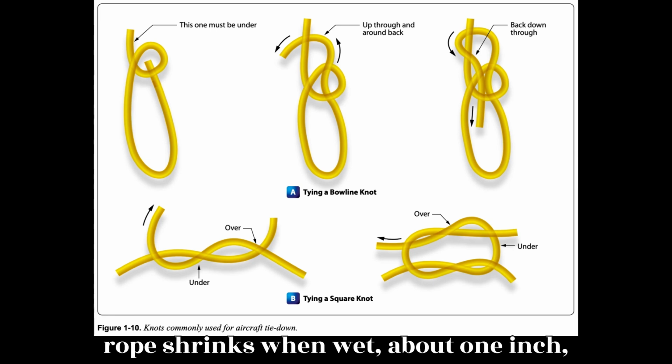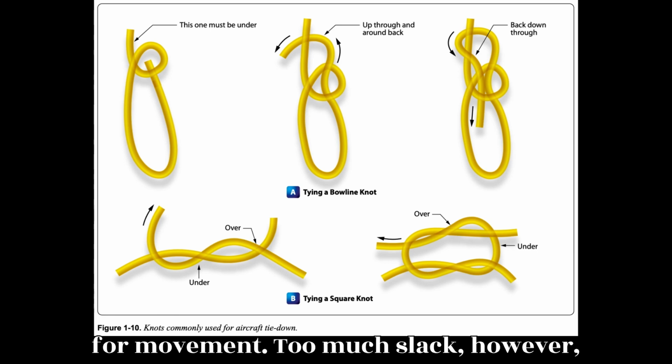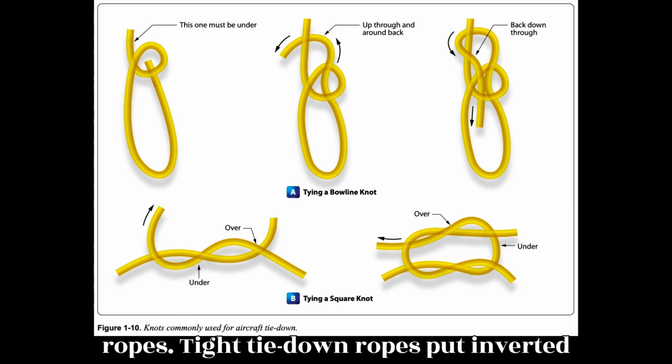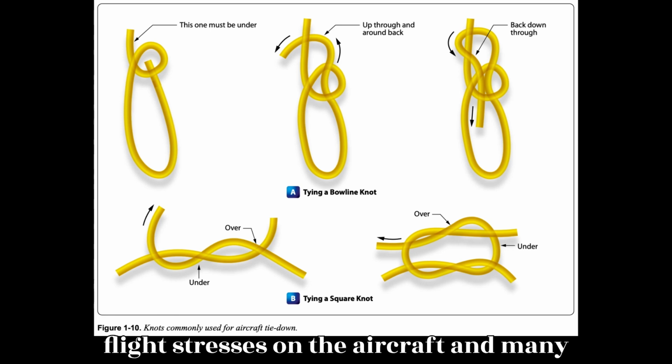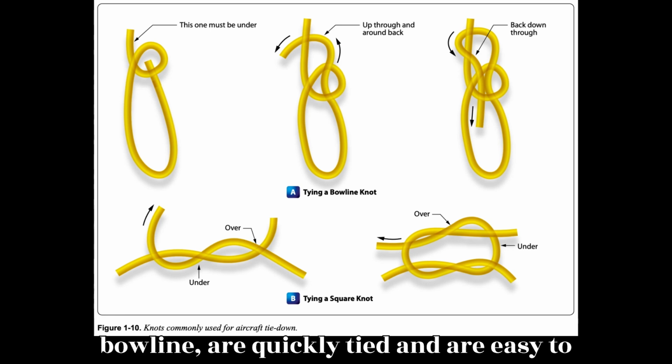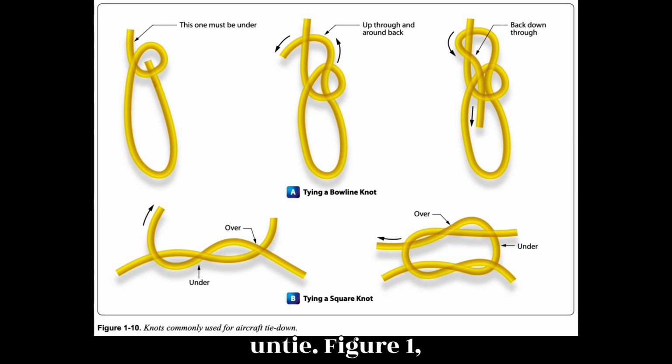Since manila rope shrinks when wet, about 1 inch of slack needs to be provided for movement. Too much slack, however, allows the aircraft to jerk against the ropes. Tight tie-down ropes put inverted flight stresses on the aircraft, and many are not designed to take such loads. A tie-down rope holds no better than the knot. Anti-slip knots, such as the bowline, are quickly tied and are easy to untie.